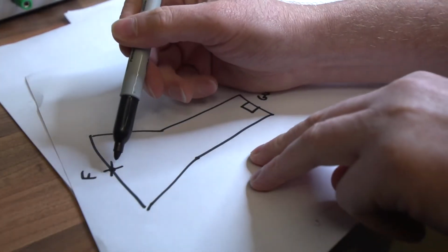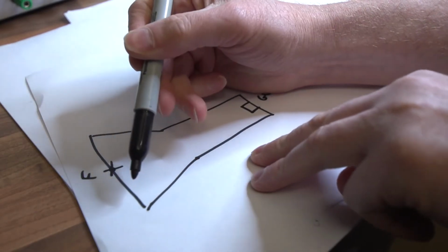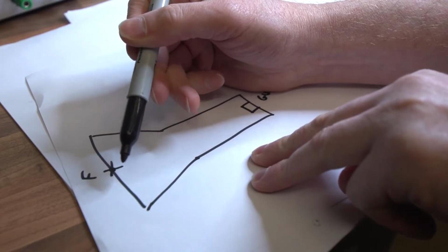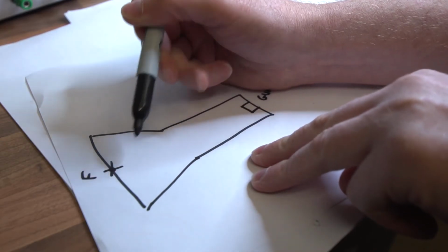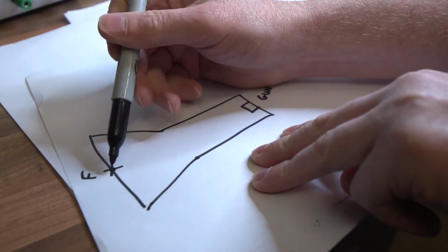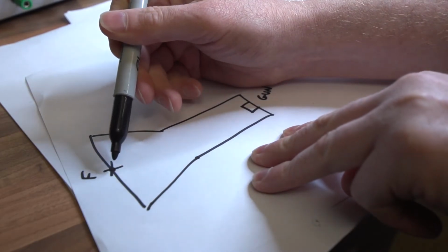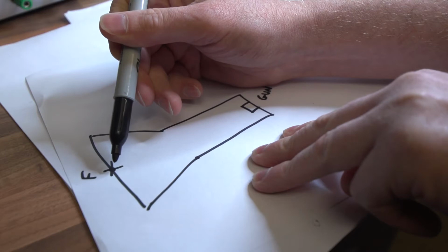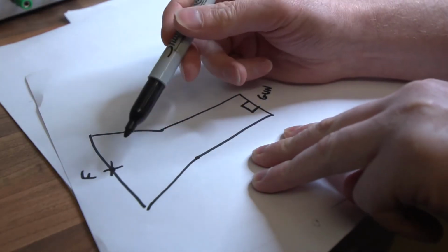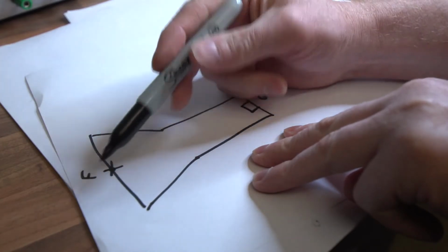Now the electrons, when they hit the front of the tube, there's a phosphor coating on there, and it illuminates light. So in effect, it's converting the electron beam to light, and that's the green dot that you saw earlier on the screen. That's exactly what's happening. But obviously we can move the dot. We can move it up, down, left and right.